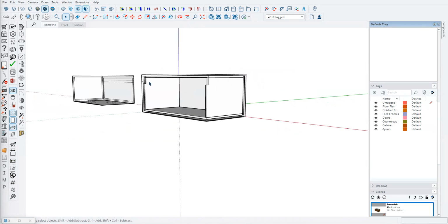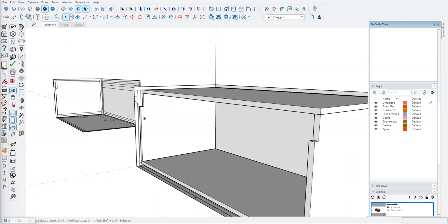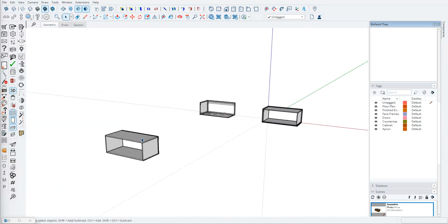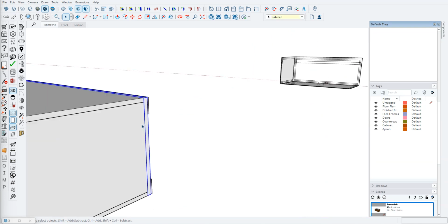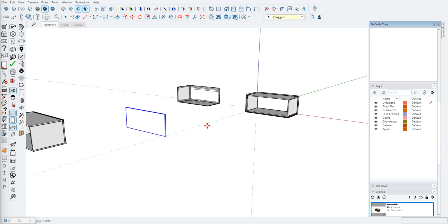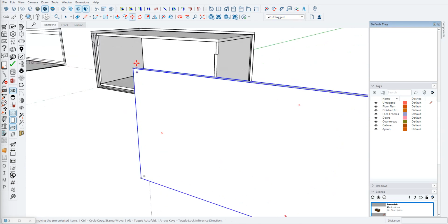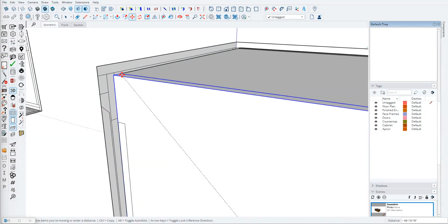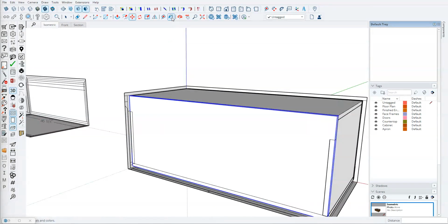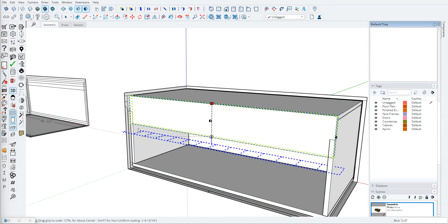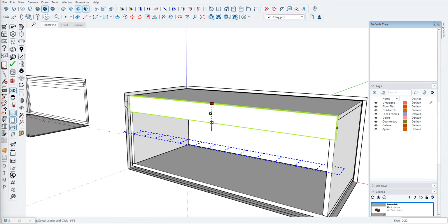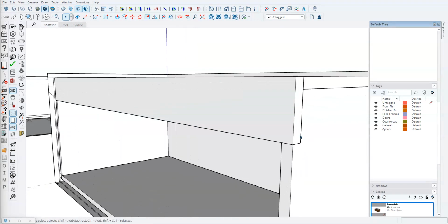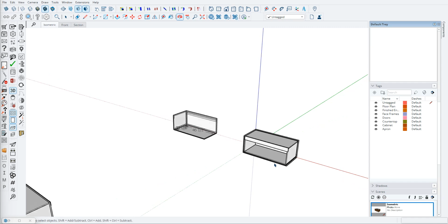So now that we have that notch, now we need to get our apron piece in there. So again, I can just take the back, because it's already in that vertical position. I can just drag this here where it needs to be, okay, and then use the stretching tool again, and just using the inference system, drag it right to where it needs to be.